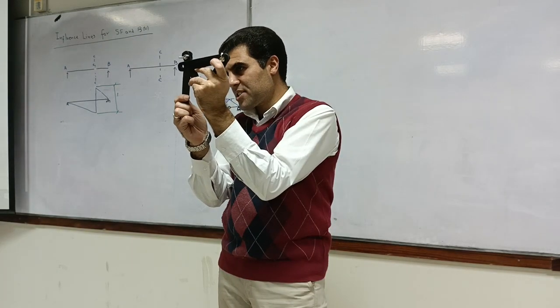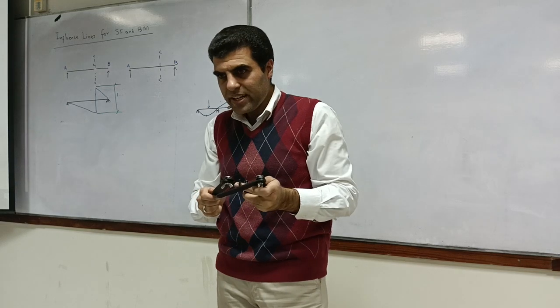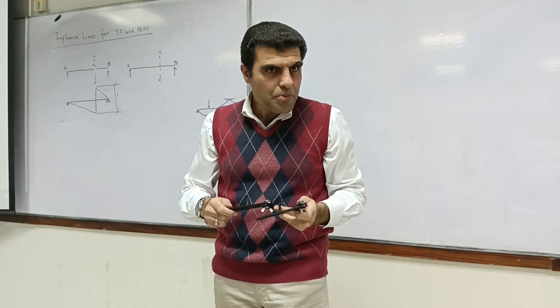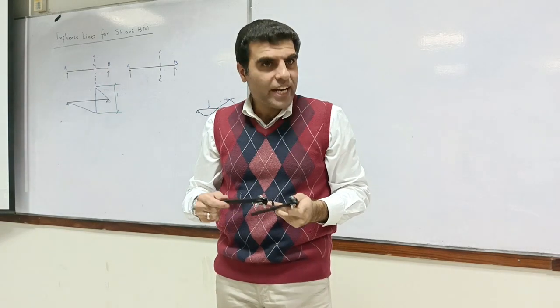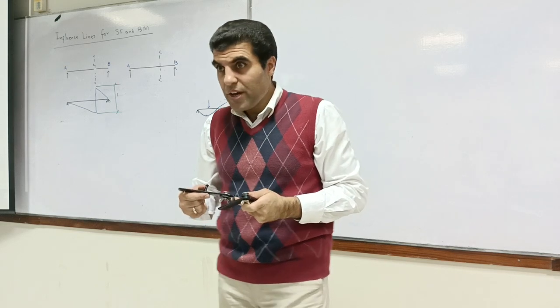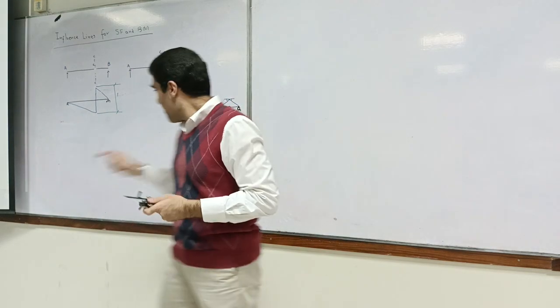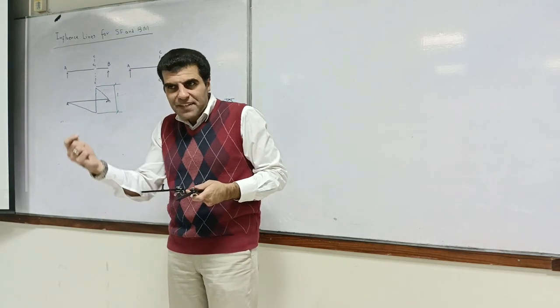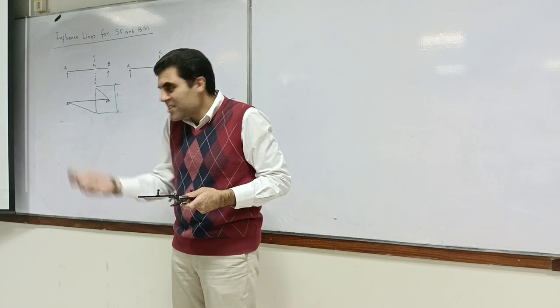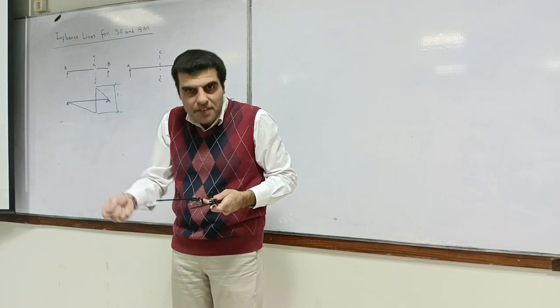Okay, I can have it in this direction. I mean, the slope keeps on changing. Do you agree? Yes. Do you understand my point? Yes. If I have got an intact section where bending moment is not released, then my slope at a particular point, slightly to the left and slightly to the right, is the same. That's the definition of an intact curve, isn't it?